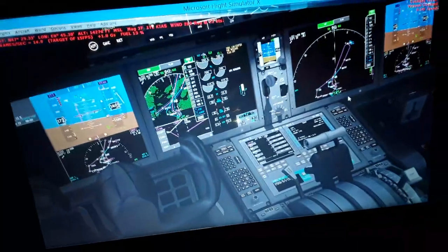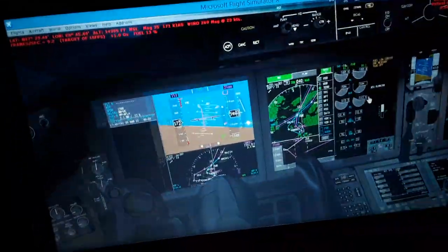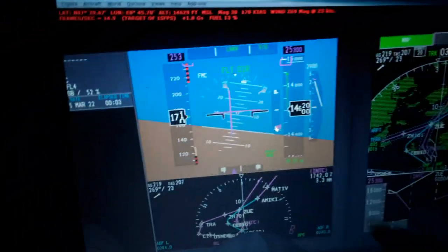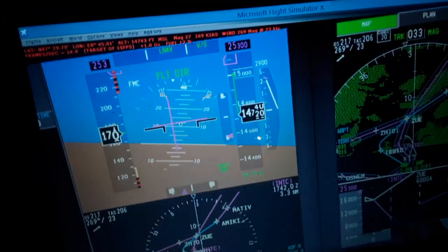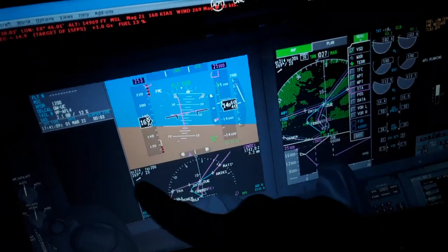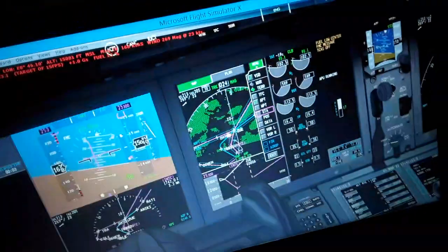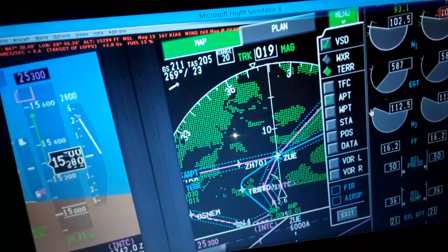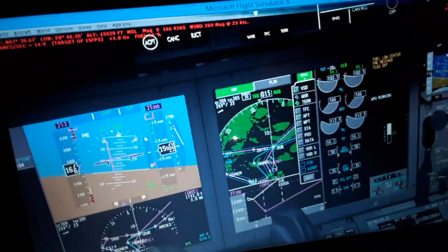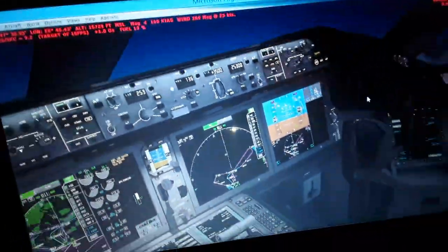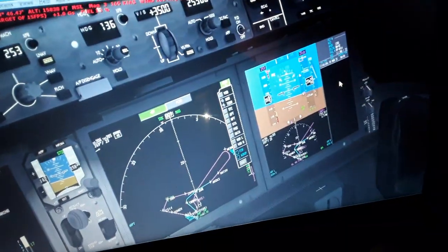So the indications here we need to align with the air data here. So you can see again the airspeed, the stall speed with the amber and red indication here. So we need to avoid the stall. The climb rate over here, 2,900 feet. The wind direction 23 knots over here. In the next waypoint we have to follow the distance to the next waypoint over here. We have it here actually, in this display also. The other side display, as you can see.